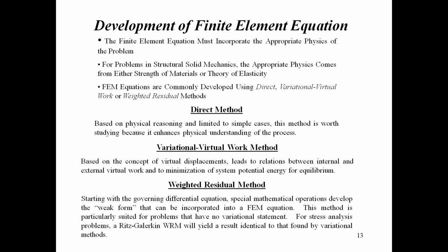So, development of the finite element equation. The finite element equation must incorporate the appropriate physics of the problem. For problems in structural solid mechanics, the appropriate physics comes from either strength of material or theory of elasticity. So the basis for the finite element equations is nothing but the strength of material or theory of elasticity. FEM equations are commonly developed using three methods, that is direct, variational or virtual work, or weighted residual method.